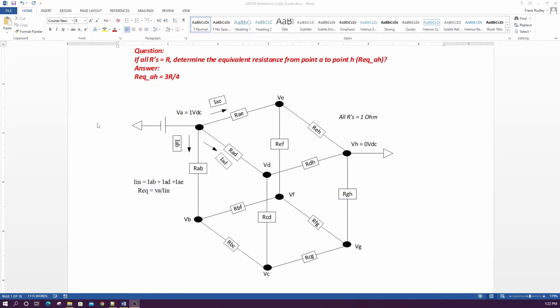So anyway, we consider our power source coming from the voltmeter or ohm meter, or we call it a voltmeter because it's a multimeter. It does resistance. So I have it represented by a battery, and then it's applying a voltage to this node. So this node is known. You know what this node is because that's what the voltmeter is applying. And you also know this node. I said this was ground, so I said this was 1 volt and this is 0 volts. So anyway, we have 12 resistors and we have 8 nodes, and there are going to be 8 equations that we need to look at for this.